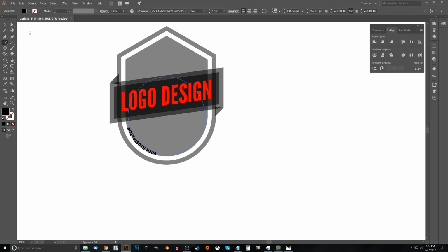And what I'm going to do now is we have to position this text so that it's not where it is. It needs to be going on the inside of the circle and over here. So to do that, I'll come up here to the Direct Select tool and click on that. And once we click on that, we're going to get these two little nodes right here. And wherever those two nodes are for you, go directly across that circle and you're going to see this blue line sticking out. And what we want to do is grab this blue line, and it's going to act as a little handle for us to place where the text goes. And if you notice, wherever it's blue is where the text is going to be. So I'm going to place it right about there.